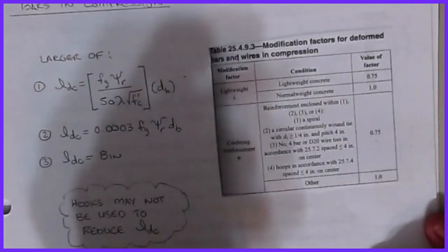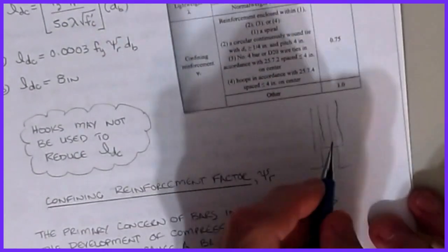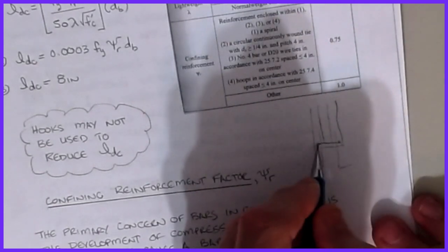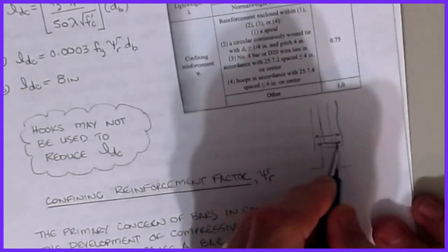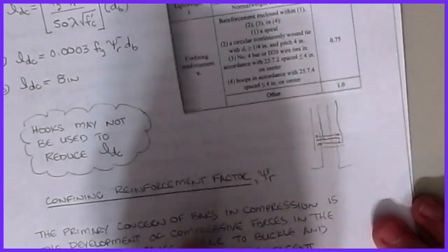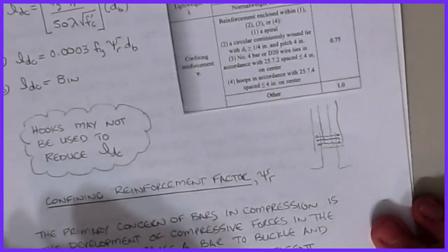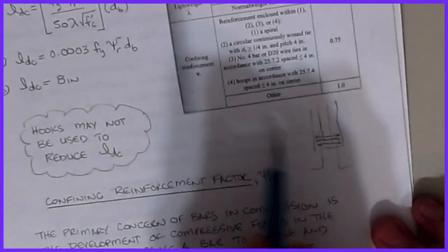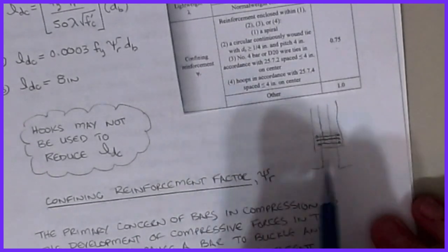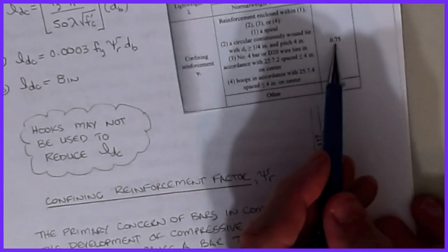then I can reduce that distance as well. That's one of the reasons a lot of times at the bottom of a reinforced concrete column, you may have your anchor bolts coming up and then these bars coming in as my splice, and they'll put in some very tightly spaced bars at the bottom or anywhere that splice is being done, because the splice is based on the development length, and I want to get every little bit out of this that I can.